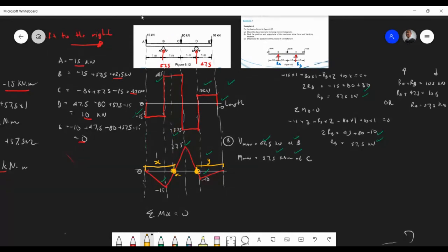Okay, so what we would use are 15 kilonewtons, 57.5, 80, 47, and 10. Just these forces. We can neglect the other forces on the end. Don't worry about all these forces here. Your thinking is still right, but just work on all the forces to the left. So I ask you, you agree with me that this distance here is 1 minus X, this piece here.